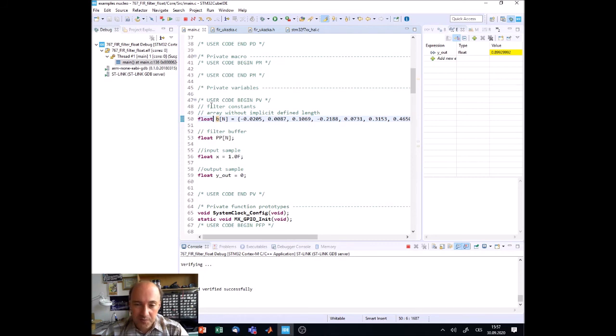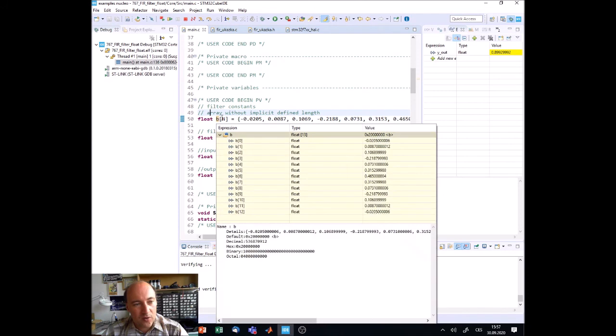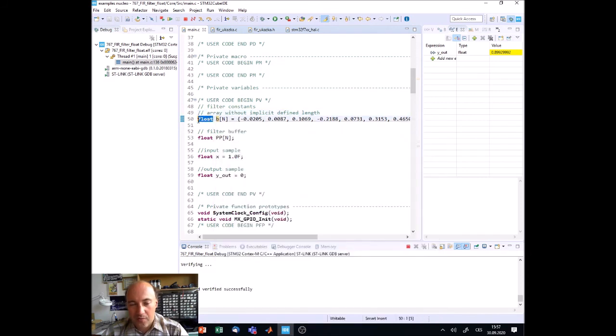If your CPU has support for floats, there is basically no speed decrease if you use them compared to integers. Well, there is, but not that large. But if your microcontroller does not have support for floats and you still use them, your program will be, let's say, 1000 times slower.